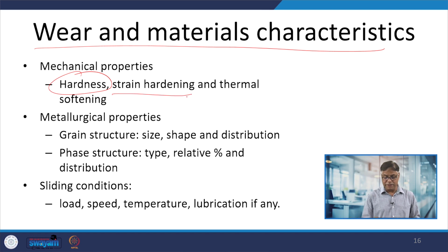If it does not have that, then it will lose its resistance to wear. Strain hardening behavior: at high temperature, the material will not experience strain hardening, but will certainly experience softening. If the metal gets softened easily, does not get hardened, and the hardness is lower at a higher temperature, then under the high temperature conditions in which the guides will be working, the material will not be able to survive effectively.